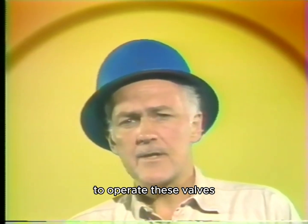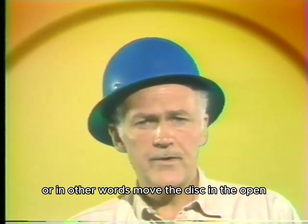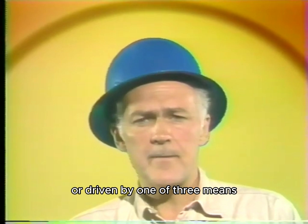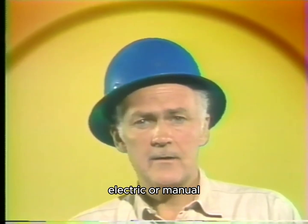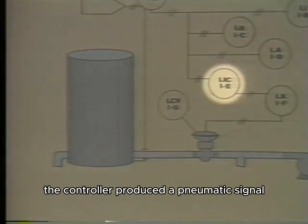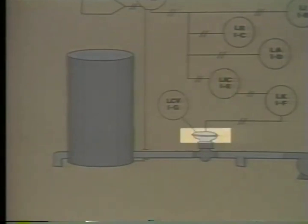To operate these valves, devices referred to as actuators are used to change valve positioning, or in other words, move the disc in the open or closed direction. Actuators are usually powered or driven by one of three means. The power sources are either pneumatic, electric, or manual. As you may recall, in our level control system diagram, the controller produced a pneumatic signal that caused the pneumatically driven actuator to open or close the level control valve.